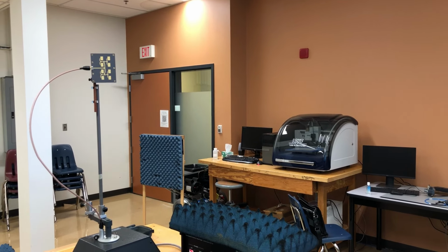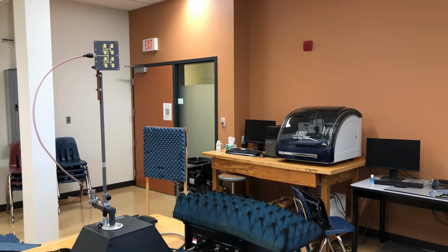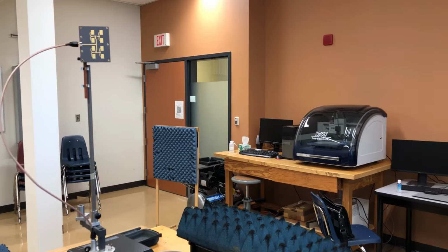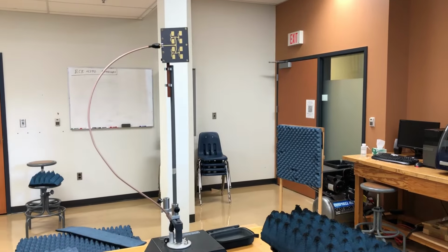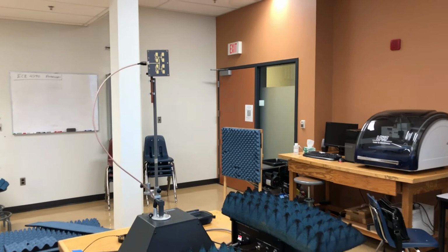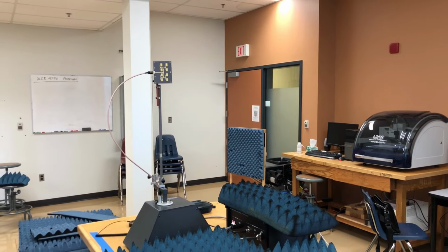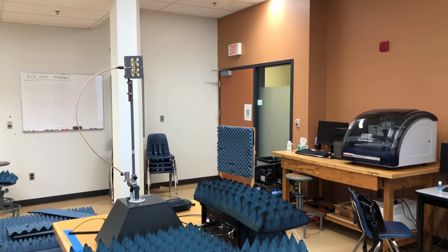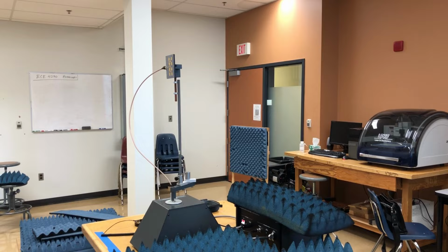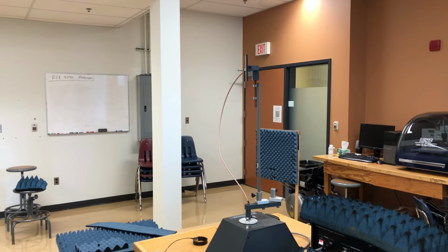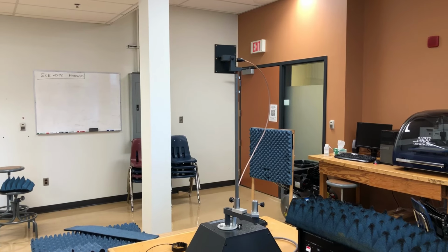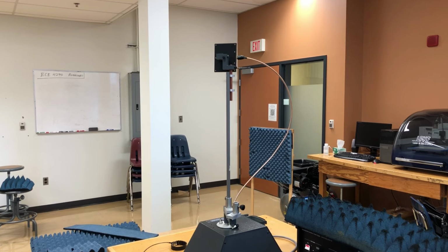So let's go and see what the radiation pattern of this patch antenna will be. Just before maybe seeing the software, let me press the data collection button, and then you can see a little bit of movement of the antenna. You've seen that several times, but let's briefly check that. So I've just started the RF generator, and now I'm gonna press the data acquisition button so that the transmit antenna starts to rotate. So as you see, it actually goes to the back, so it's going toward the back lobe collection. So that's my back lobe right now. Later on, you can see that in the software.